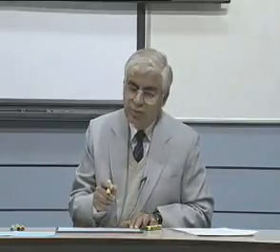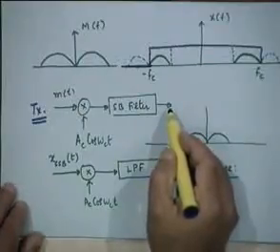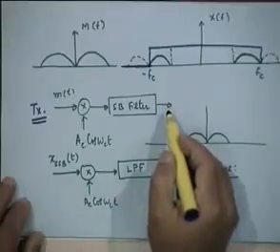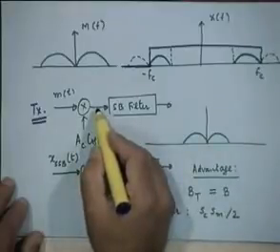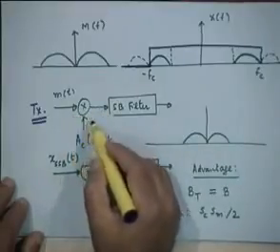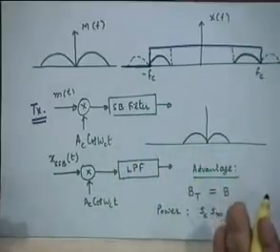Now, before we proceed further, let me ask you a question. Suppose I ask you, tell me what will this waveform look like in time domain? Can I write a mathematical expression for this waveform in the time domain? The answer is not that easy anymore, right? Because I can write the expression here. That is simply the product of these two waveforms. But what kind of waveform I have after this single sideband filtering is not so obvious. Now we'll take that up as the next job to do, and when we do that, we'll find that once we have this mathematical expression, it also gives us another method of generating SSB signals.